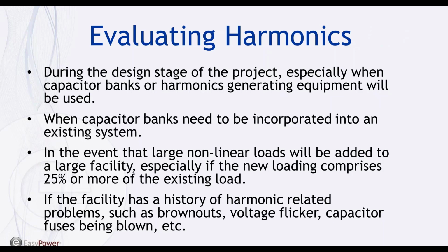Well, it is always best to perform an evaluation of harmonics during the design stage. This is very true if large capacitor banks, which are typically used for power factor correction, or other harmonics generating equipment will be used. Also, if capacitor banks will be incorporated into an existing system, a harmonics analysis or evaluation should be considered, especially if 20% or more of the load includes other harmonic generating equipment.